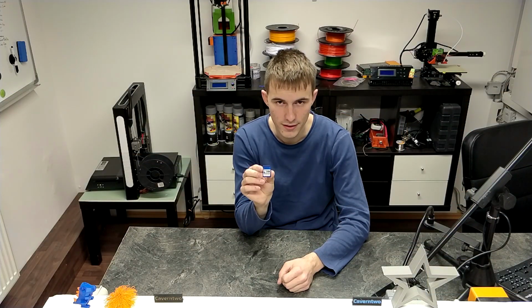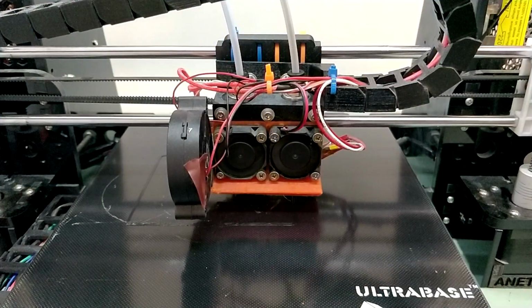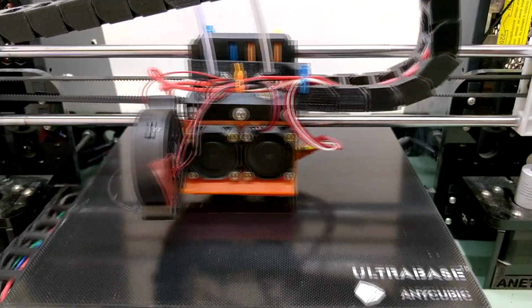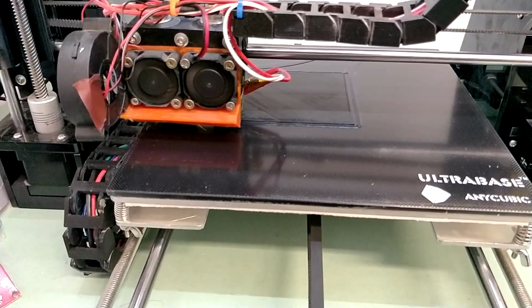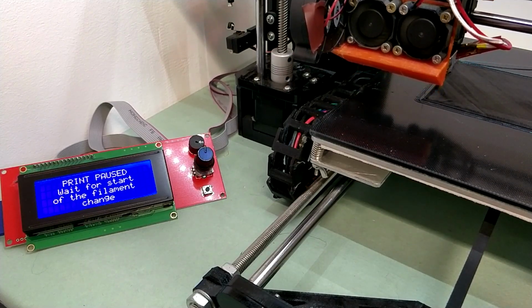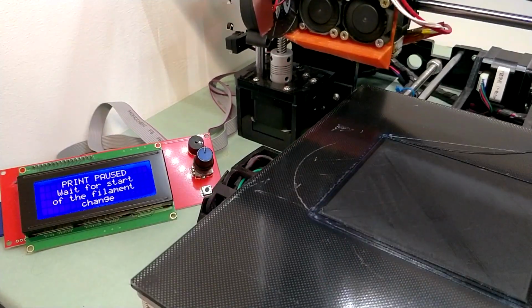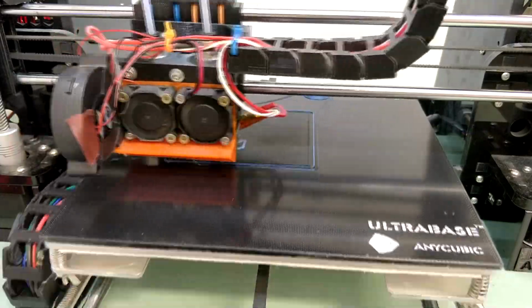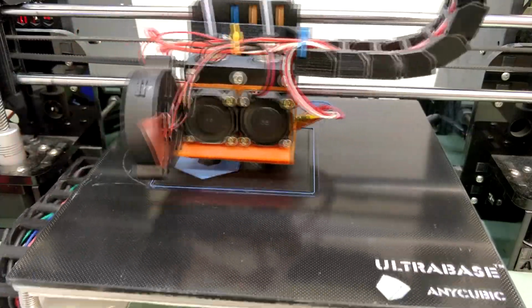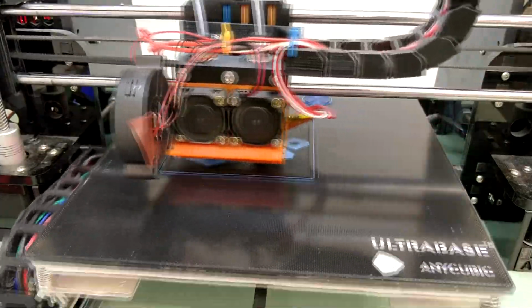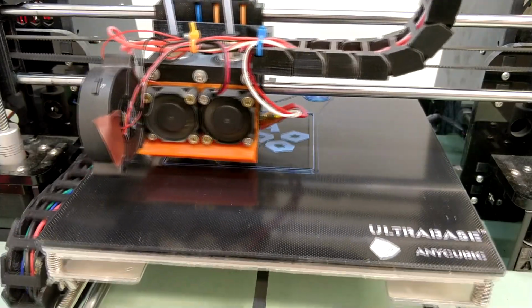With the model saved on this SD card, let's go over to the ANET A8 and start the print. The print is starting out pretty nicely and I use 2 black layers at the bottom to keep all parts of the logo together. After 2 layers, the M600 triggers and it's time to change the color to the light blue. Now that the base is finished, the logo is being printed. You can see how nicely both blue filaments get painted onto the black surface. Furthermore, the halfway translucent darker blue looks almost black here.